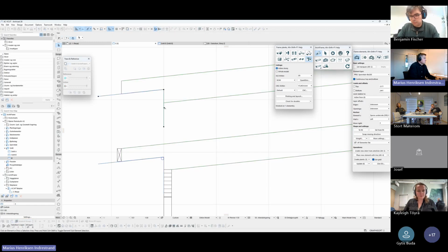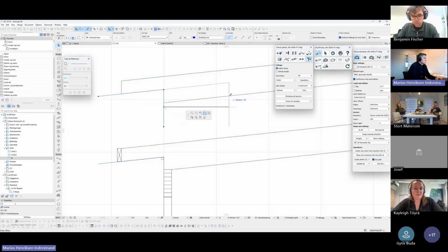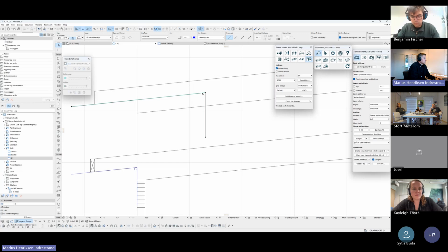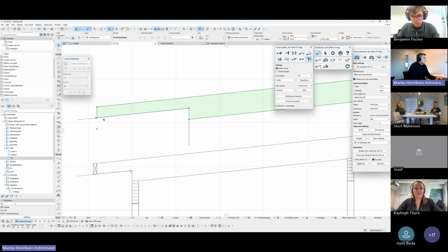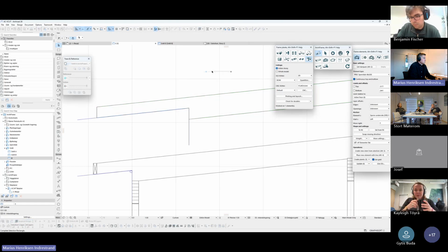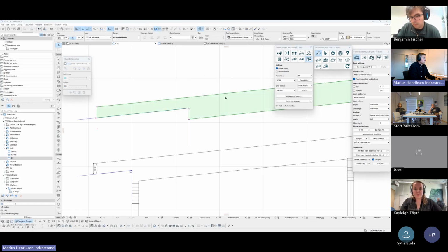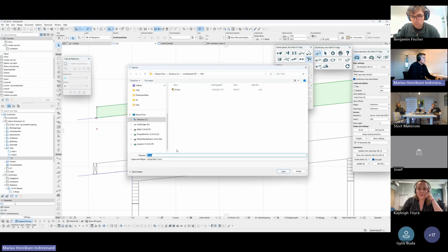and do an example. So let's say you have a really long overhang or eave. Just move this. If you send this to the Hundegger, making a dado cut here, this discharge piece will block the belt. So just exporting this and opening in SpeedCut.